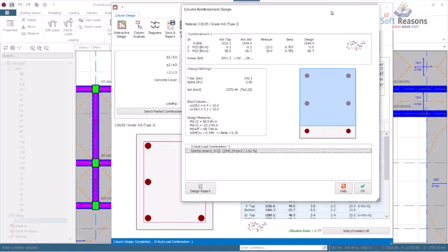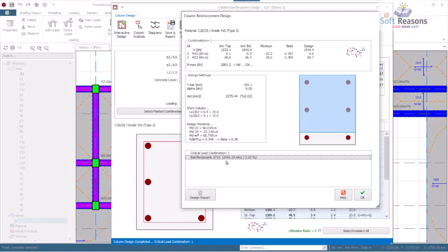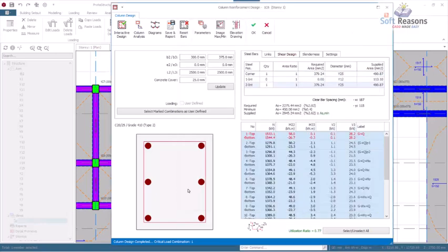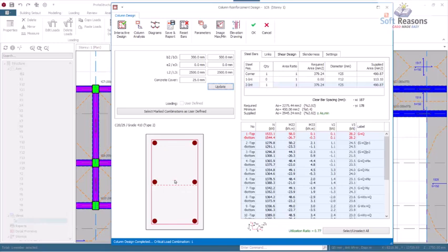So for you to now have an economical design, because this is not economical at all, you have to close this dialog and then come over to where you have the sections. Select these section provisions, and then you can key in, for instance, 500, meaning we are having a column section of 300 by 500. Click on update right here to now have this rectangle in this shape, after which come over to where you have the rebar, this reset rebar.